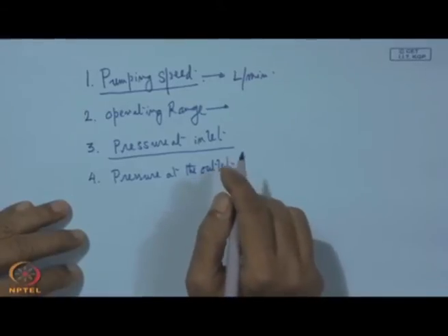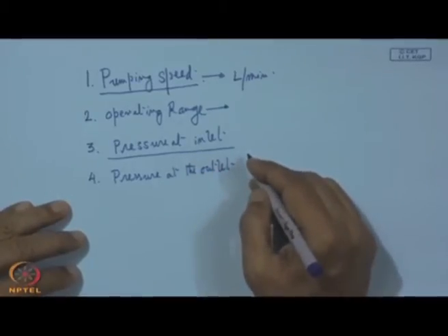This point is important in that there are many pumps which cannot deliver the pressure at the exit point above atmosphere. In that case we need another pump as a backing, so that it can be coupled in series on the downstream side, and that can raise the pressure of the residual gas above atmosphere, and then that can be thrown outside.